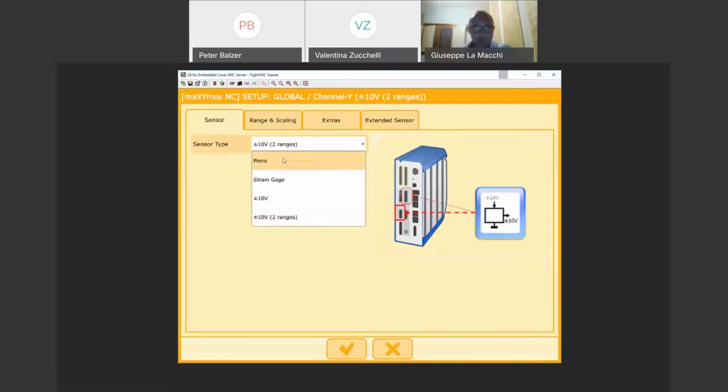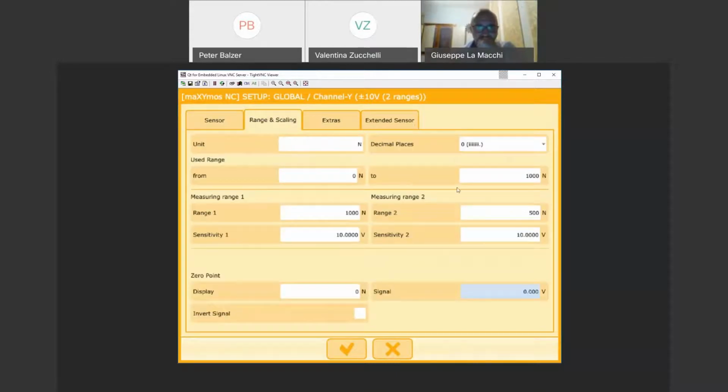The problem is if we would use this piezo cable, well, it's very thin and it's really fast broken. That's why we prefer to apply a charge amplifier directly in the housing of the joining module, so we can use an easier cable with a bigger diameter. Okay, so this one is the real setting for NCFT.